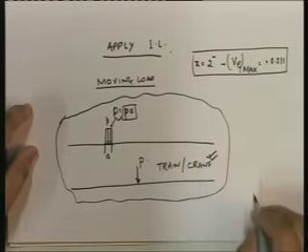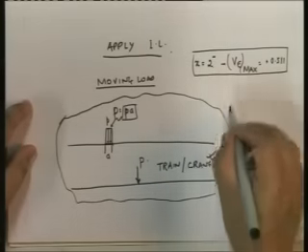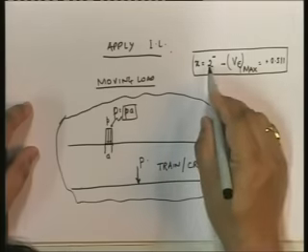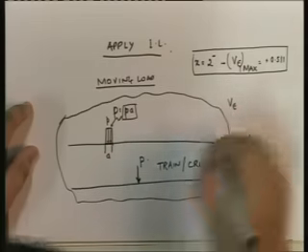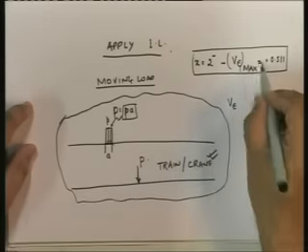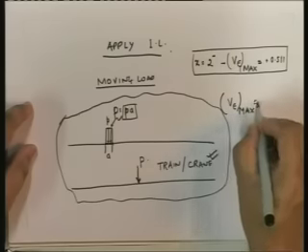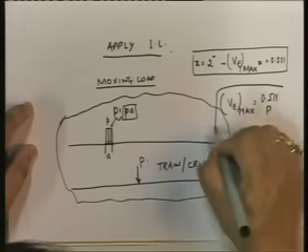For this moving load, we know what the maximum VE is going to be. We know where the load has to be applied. It has to be applied at this point, and once we apply the load at this point, you can do an analysis and you can get that VE max is equal to 0.511 P.